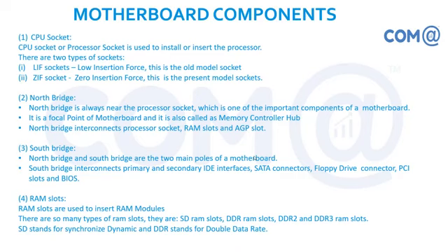So North Bridge mainly takes care of this operation between the processor and video and memory. This communication will be processed here, and that's why it is very close to your motherboard processor. South Bridge handles the other controllers, IO controllers, IDE controllers, or hard disk storage devices. So that is also taking care of the communication between the devices and the processor.